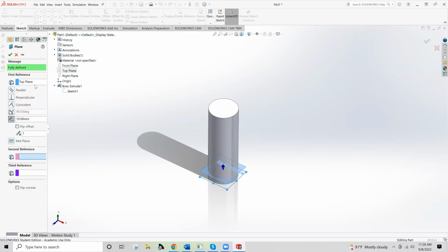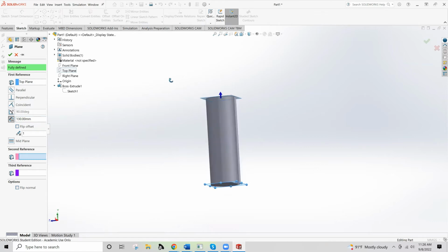For this, I'm going to show you how to do a simple reference geometry as an offset plane for that same height. So distance is going to be your default. And we said this was 130 millimeters. And one of the big advantages to having a mouse is you can hold down the scroll wheel and move this.